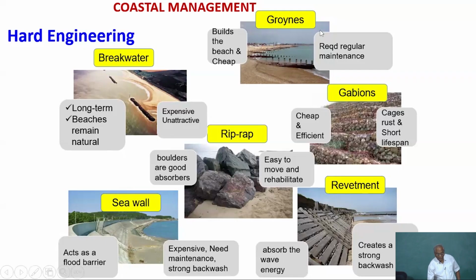So if you look at the groins, these are the groins. The groins can be of trapezoidal section, natural rock, or you can even have palmyra tree trunks driven in, if it is to serve for a few years. The main idea is that the length of the groin should extend beyond the surf zone, because most of the sand that is moving will be within the surf zone, that is from the shoreline to the breaker zone. So this has to be intercepted.